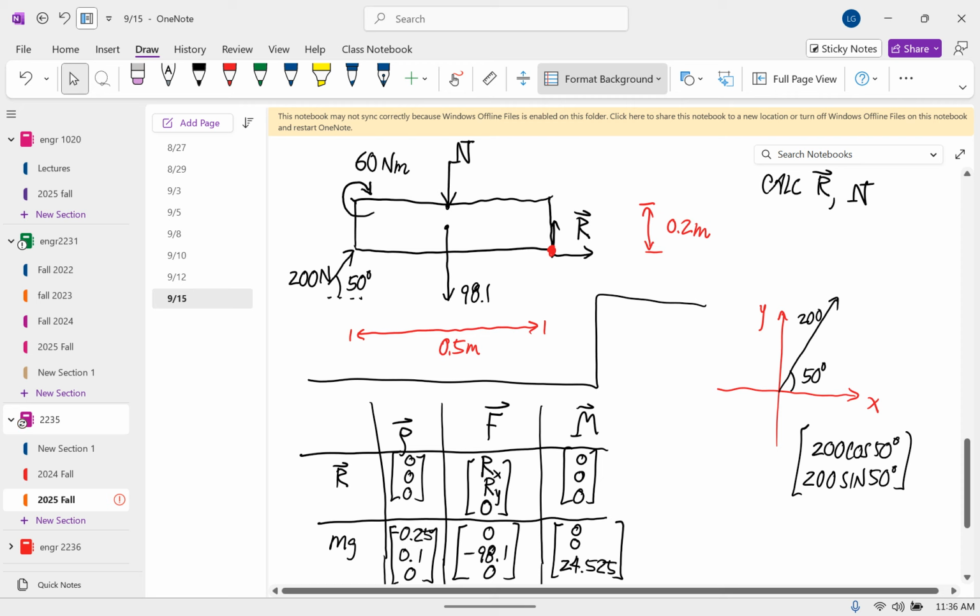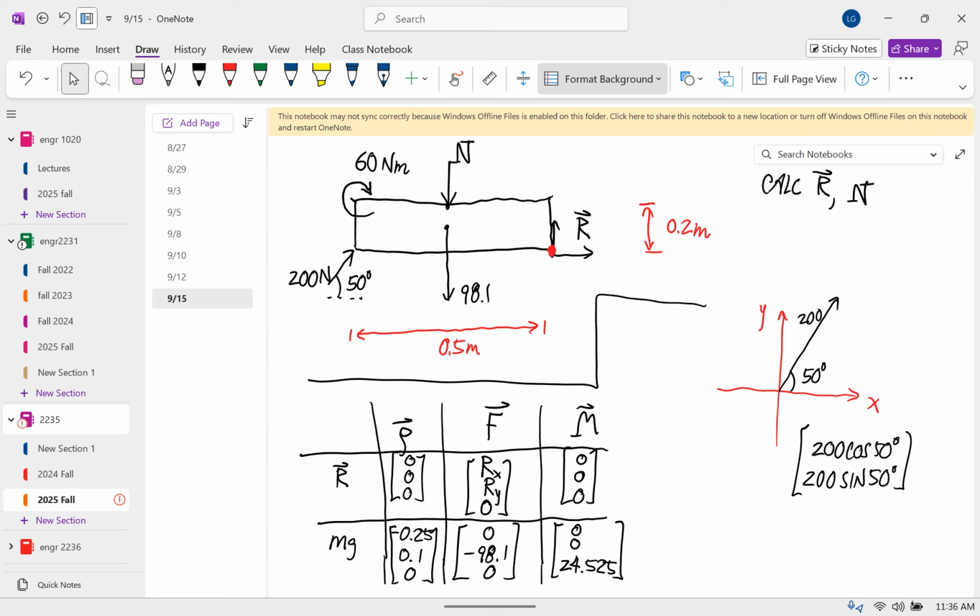And so this might be a little counterintuitive, but if you, without causing any other forces, put a screwdriver here and twisted it versus taking a screwdriver here and twisting it, the physical effect of that, as long as it's a rigid body, which we're assuming it is, is the same. There's no difference in the physical effect of the locations of those couples.